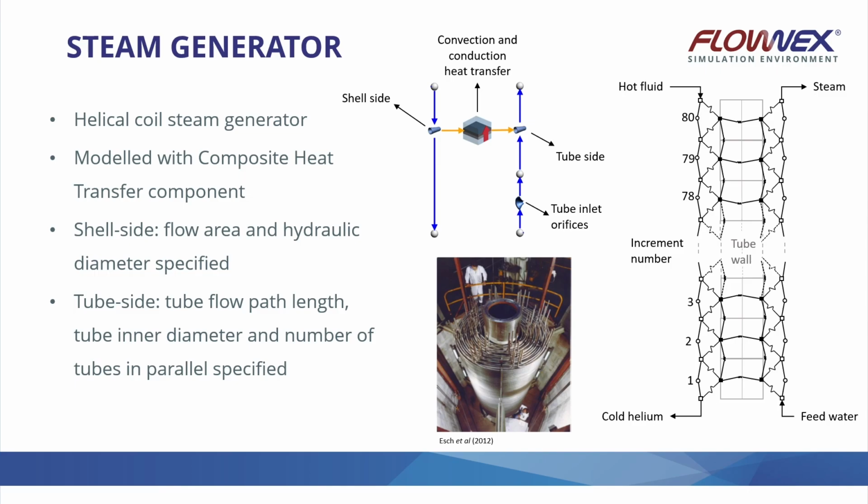In the background, the pipe and respective convection and conduction resistances are discretized as seen in the figure on the right. This means that convection is calculated at each of the specified increments, along with the conduction and cross-conduction through the pipe wall. This allows the software to accurately capture the wall temperatures during boiling, which is essential to accurately capture two-phase boiling physics.